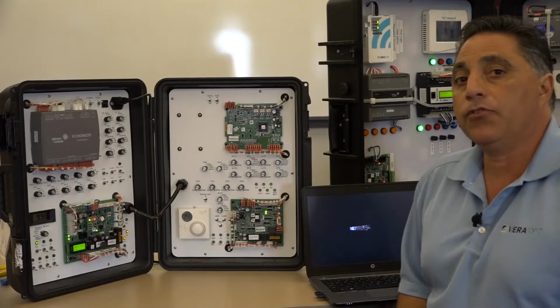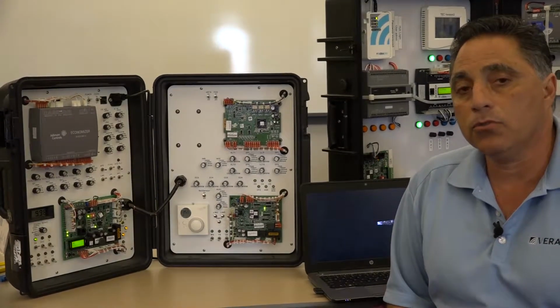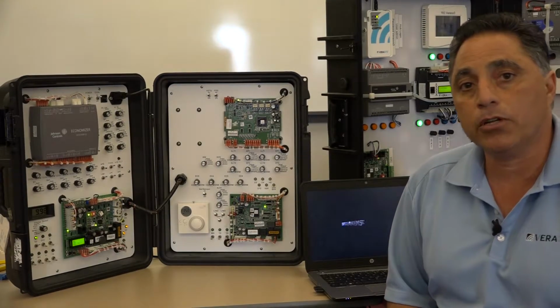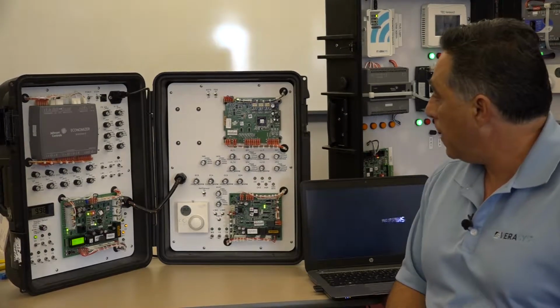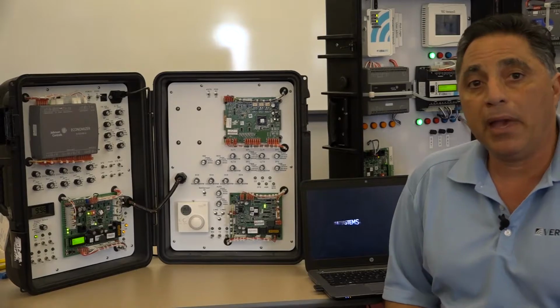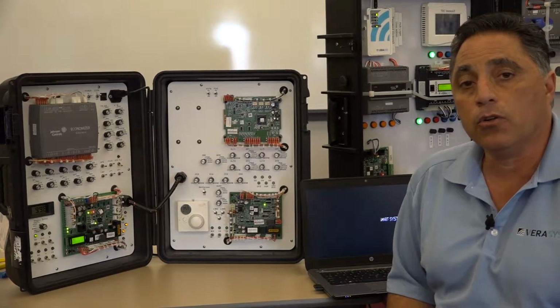But every circuit is going to have 4 sensor inputs. You will have 2 pressure inputs and 2 temperature inputs. So your pressure around liquid pressure and suction pressure, and your temperature around liquid and then suction temperature, you will have those inputs coming directly into this board. Those are mandatory inputs for the algorithm to be run within the controller.